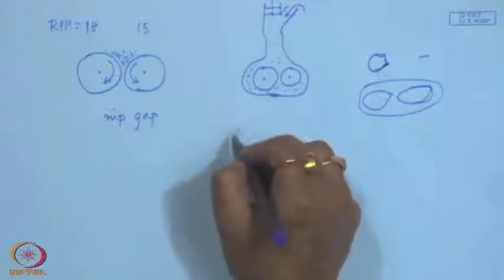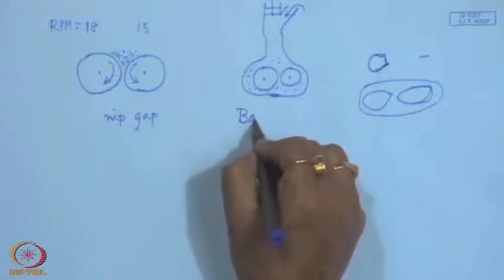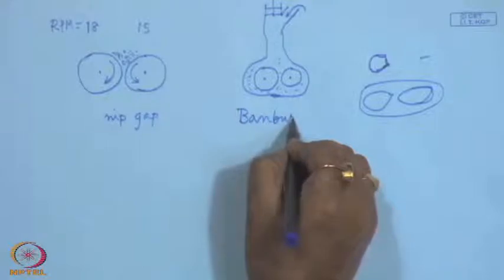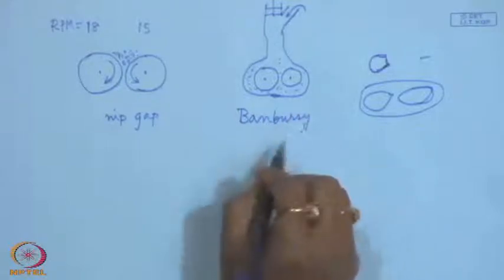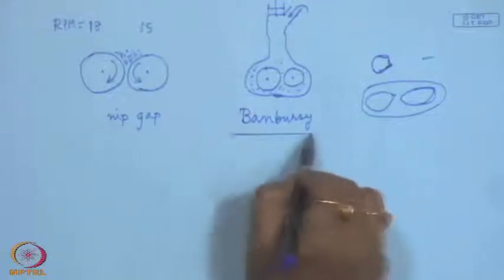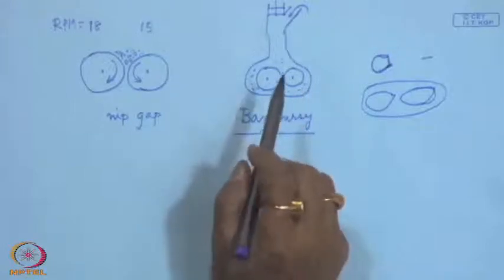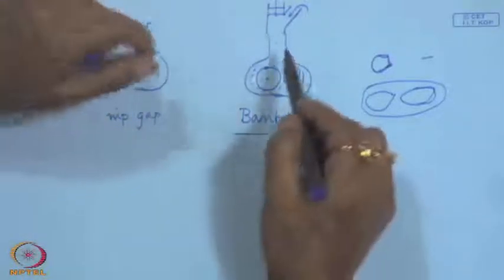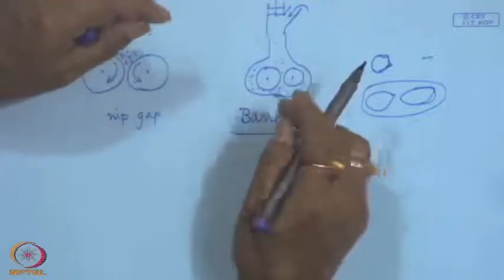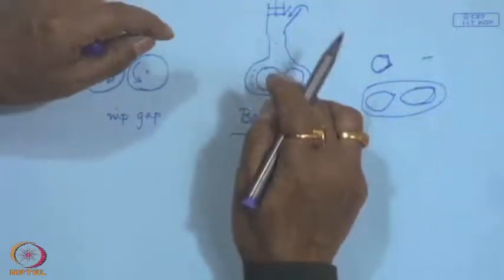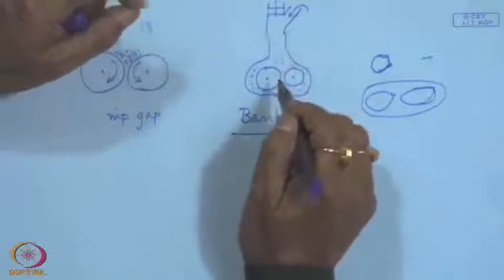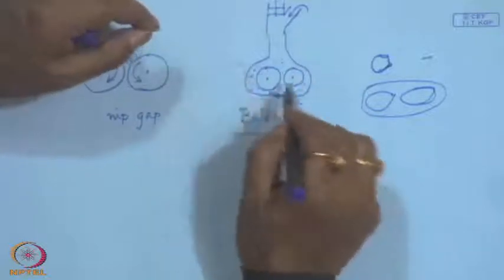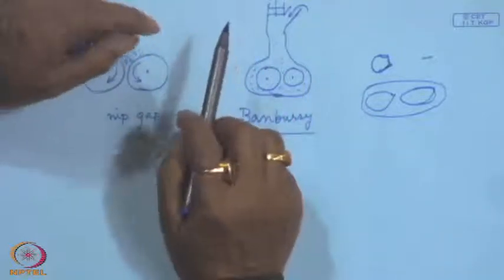There are various types of internal mixer, say the Banbury mixer, or there can be many other names. So, internal mixers or kinetic mixers are all batch mixers, that means after mixing of one batch, the second batch is to be loaded, and then mixing happens. So, through shear action we get mixing in this batch mixer.